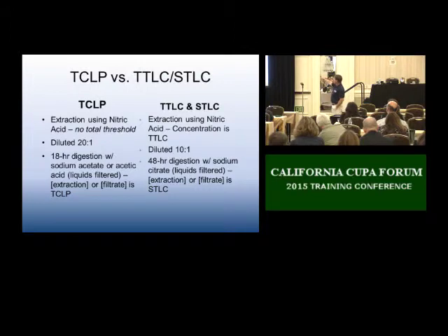Or absorption of moisture: calcium carbide. Calcium carbide is a flammable solid that's dangerous when wet. It's hygroscopic. It sucks the moisture out of the air. And when it does that, it forms a flammable gas. And if it's ever ignited, it burns very persistently and aggressively. Now that solid is a flammable solid dangerous when wet. So if you have a DOT hazard class that's 4.1 or 4.2 or 4.3, and you go to get rid of it, that's probably an ignitable waste. Even though it's not a liquid, it's ignitable.